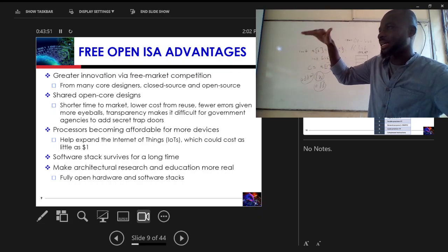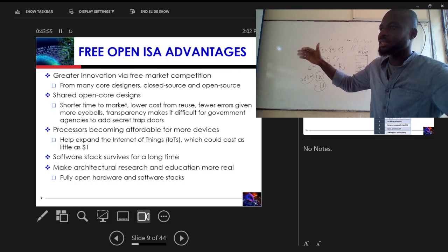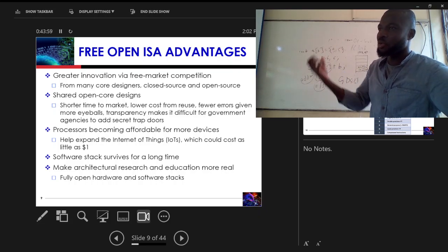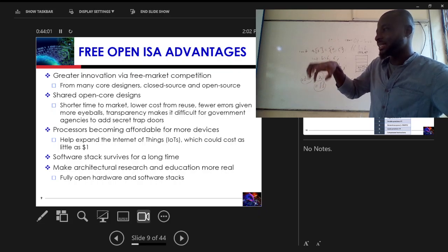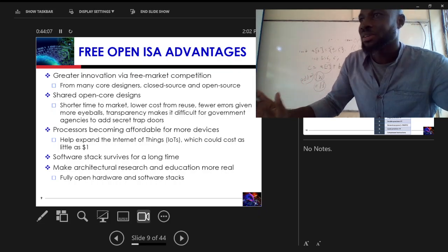That's the process you go through to manufacture an actual chip. You code in what they call a hardware description language, Verilog or VHDL. You use a commercial tool to extract the gates from your code. Then there's a file that you send to the foundry. The foundry will now manufacture a chip and ship it to you. So that's how it's done.